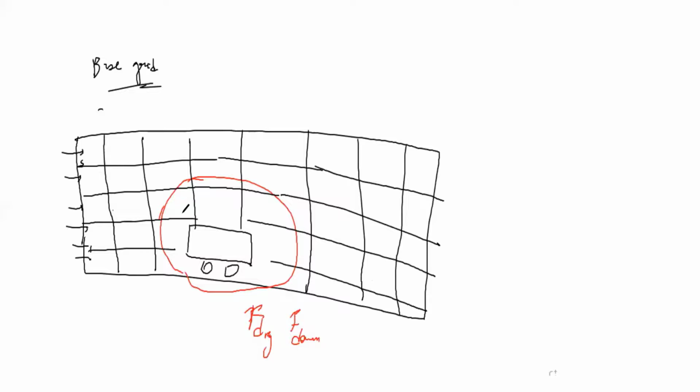Now my concern is I want my mesh to get refined in this region only, not in the entire thing. So I'll make use of fixed embedding, volume embedding. There are a lot of things where I can basically select that.